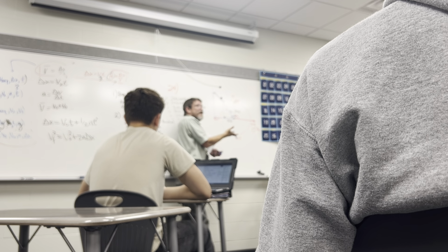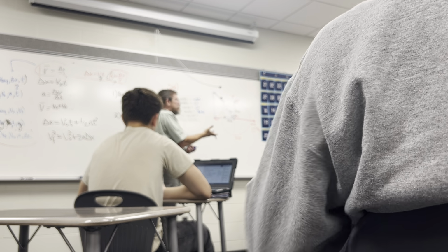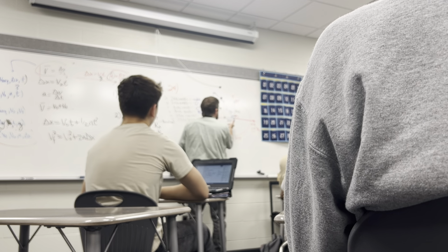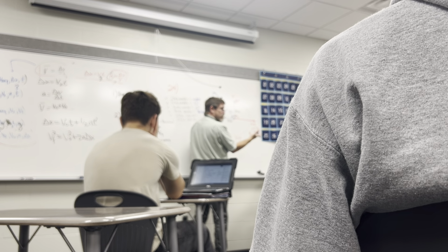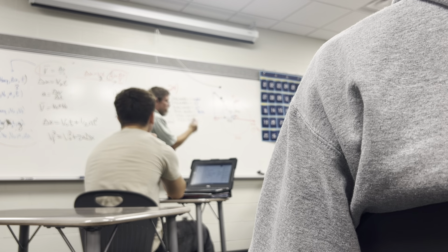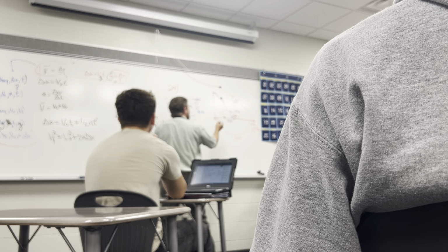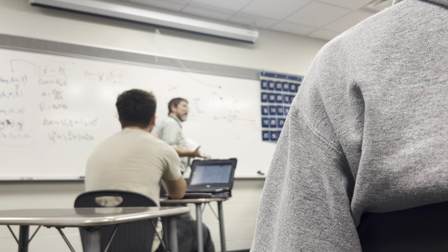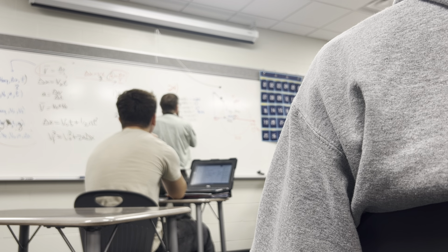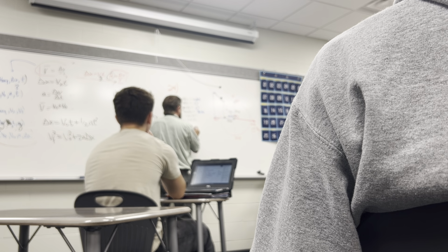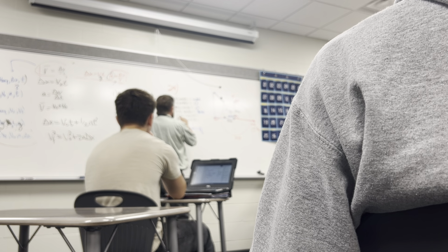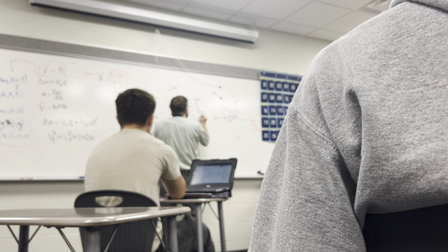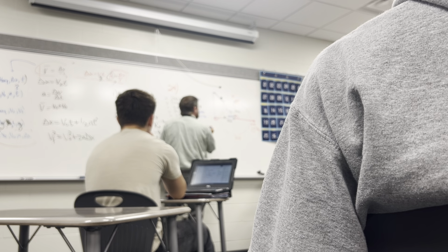These are already broken into parts. You could always just go, well, the y part's 0 and the x part's negative 20. The y part's 30 and x part's 0. It's this one, it's going off at a weird angle, but it is a 45, 45, 90 right triangle. And so when you go 25 cos 135, the cosine and the sine of 45 is the square root of 2 over 2, 0.707, and 25 times 0.707 is 17.7 newtons.